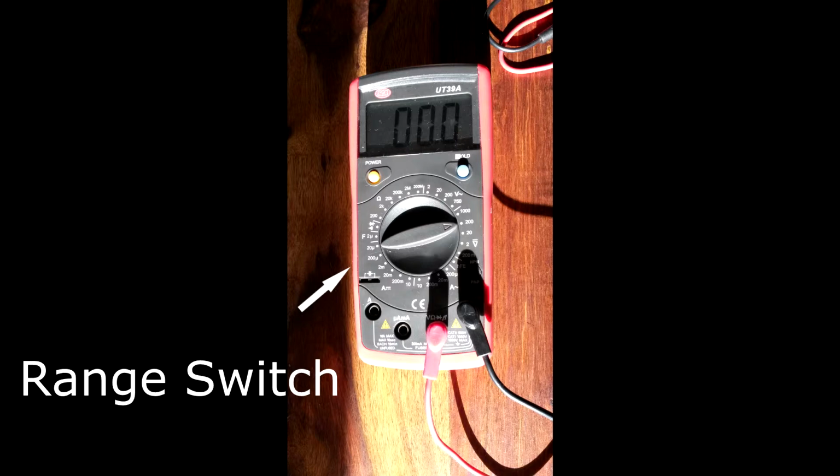Now some people might be confused with what the numbers represent. Well, as you can see in this picture, it's pointing to 200 with the straight volts. That means a direct current of between 200 volts. So the numbers just represent the range of what the parameter you're searching for is within. It's quite common nowadays to have a digital multimeter that actually has auto range. So all you really would have to do is select the function that you want, and then off you go.